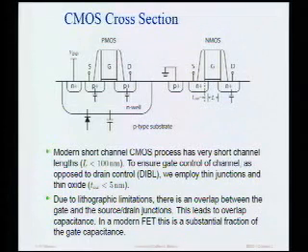So in this class, we're going to be dealing with short channel transistors, so we have to be aware of these issues. Now the other non-ideality that's process induced is this overlap region. Ideally, the gate should not overlap with the source and drain, right? The gate should control the channel. Because if the gate overlaps with the drain, we get a capacitor from gate to drain, right? Okay, big deal. No, it is a big deal. That's that Miller capacitance, which we hate, which we try to reduce.